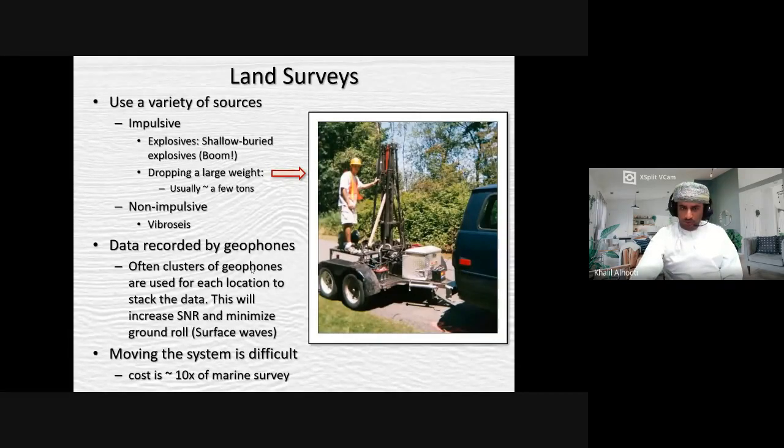So wherever you put your geophone, it's not a single geophone. They tie together like almost 12 or 24 geophones in one point. They give you one trace. It has many advantages.